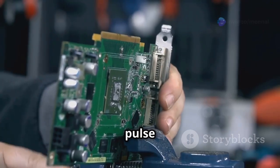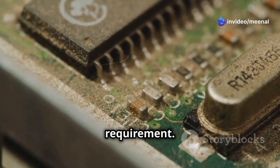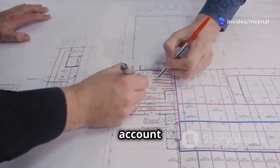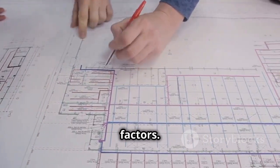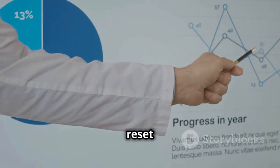Determine the optimal reset pulse width from component datasheets. Consider the component with the longest reset requirement. Add a safety margin to account for variations and unforeseen factors. A typical safety margin is 10 to 20% of the calculated reset pulse width.